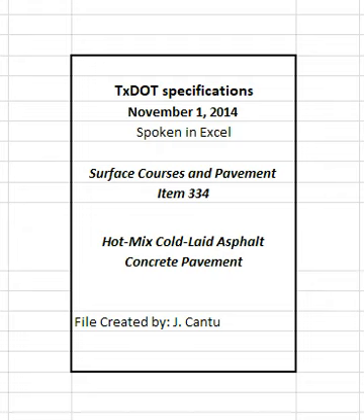Operate vibratory rollers in static mode when not compacting, changing directions, or when the plan depth of the pavement mat is less than 1.5 inches, unless otherwise directed. Start by first rolling the joint with the adjacent pavement and then continue by rolling longitudinally at the sides when rolling with 3-wheel tandem or vibratory rollers. Proceed toward the center of the pavement, overlapping on successive trips by at least 1 foot, unless otherwise directed. Make alternate trips of the rollers slightly different in length.